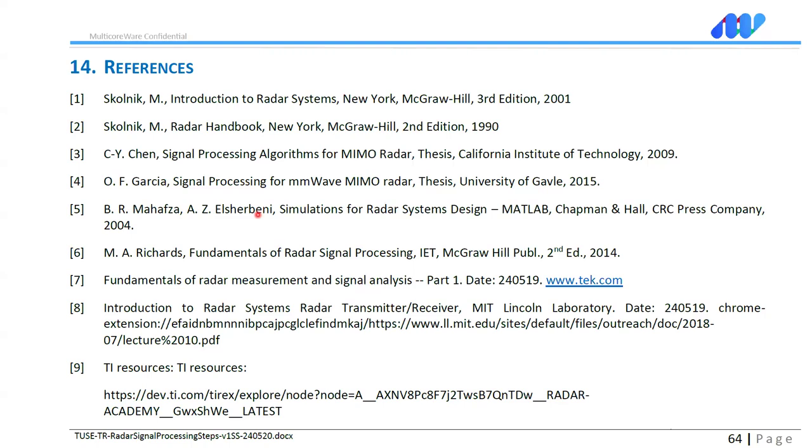But in-cabin was different. It was a smaller range, and we were able to shorten the pulse and then have a lot of Doppler gain. So I hope that helped you out, but we will have a different presentation for match filters, range correlation, and convolution operations. So please join whenever we have that presentation.